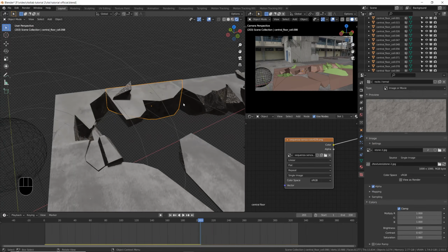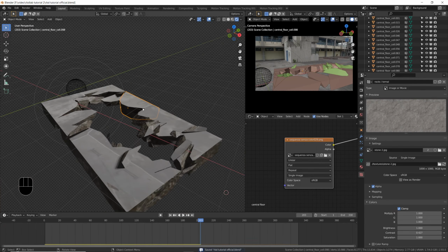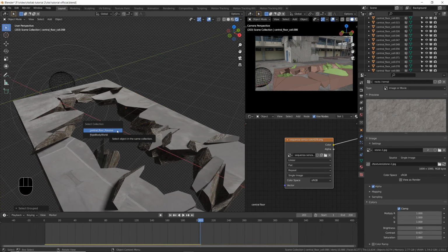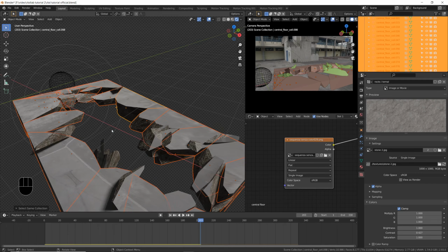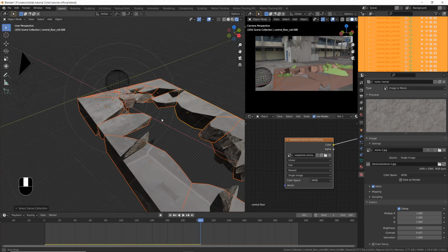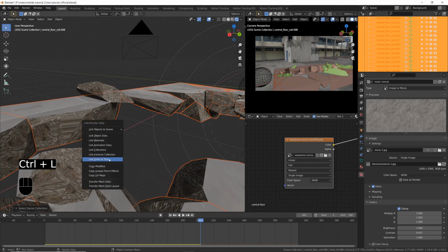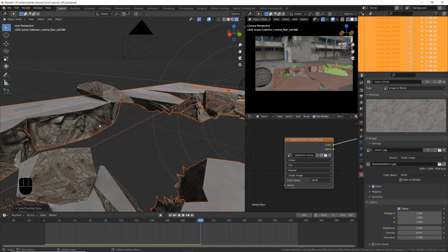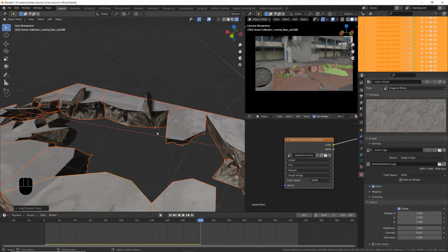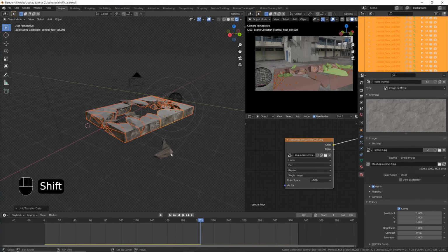Now to copy these modifiers to all the others, I just need to select this collection. So I press Shift G and click on collection, central floor passive, and you see that I have selected all the passive rigid bodies that are around. I press Ctrl L on my keyboard and press copy modifiers, and you see that all the internal shards now have the displacement and the subdivision surface. But we want to copy this also to the active rigid bodies that are flying out.